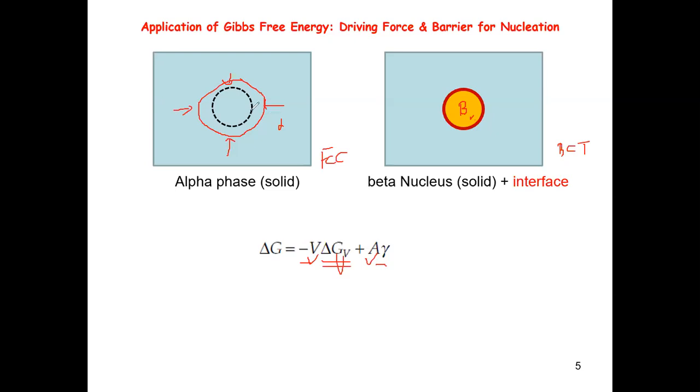It will change. Basically, suppose you dig a hole in the alpha, take that alpha and convert it to beta, and you know that beta is going to have a larger volume, right? In order for the beta to fit in the hole, I have to squeeze the beta and try to fit it in the hole. But after that, beta tries to expand, right? It's not going to be easy, because initially you add forces to constrain beta into that volume. But if you put it into the alpha phase in this hole, the forces are removed.